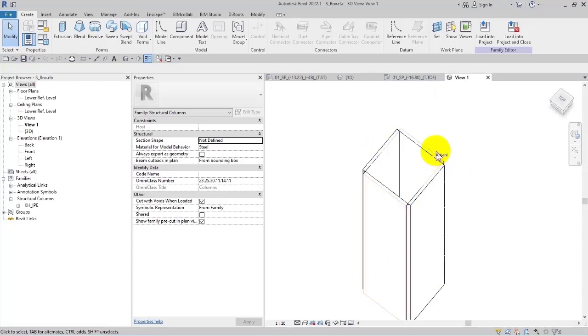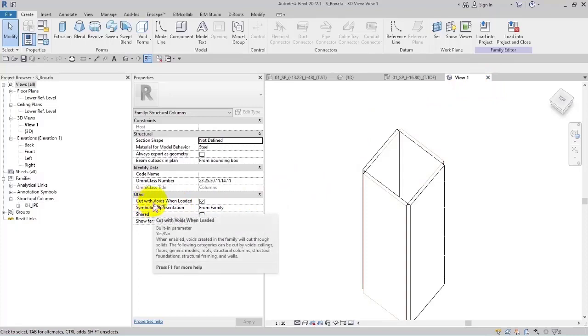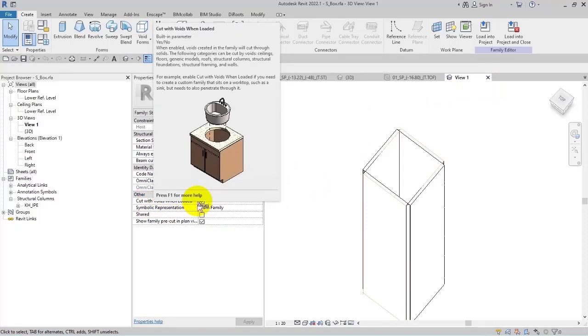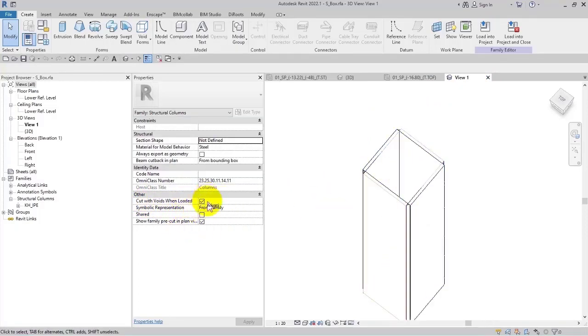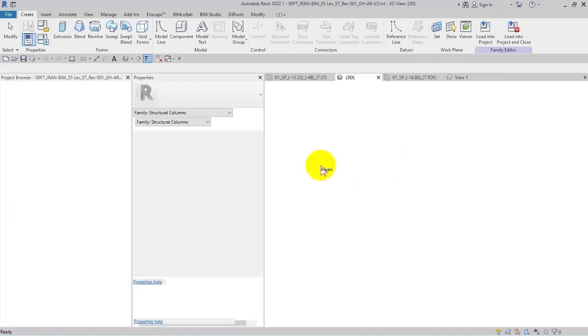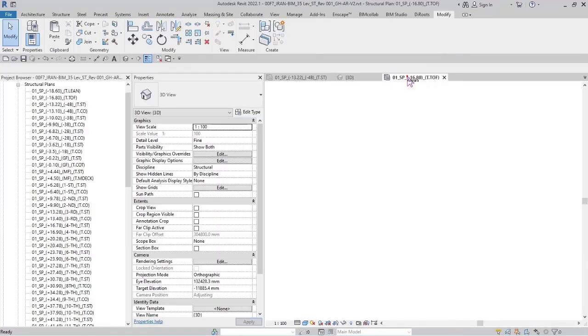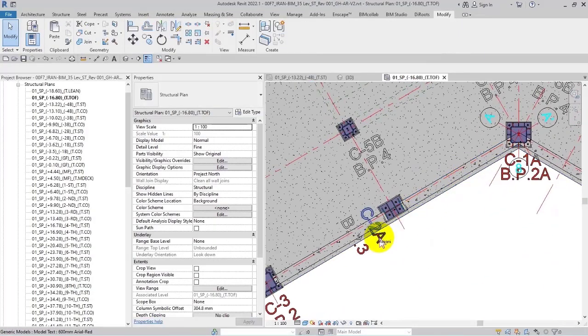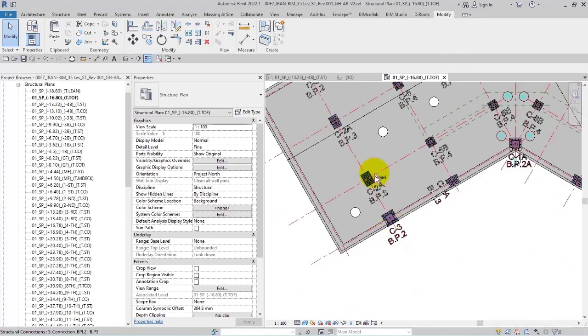And we've made this void to use it for these kind of problems in the walls and floors and connect them together. And this works when cut geometry with void is enabled, and if it's disabled, that doesn't work at all. So we've learned an important technique here that helps you to be exact in your project.